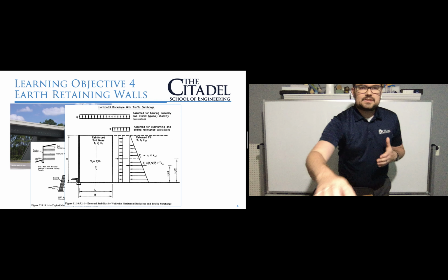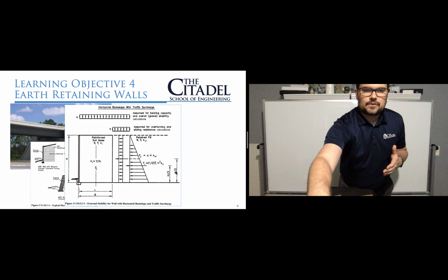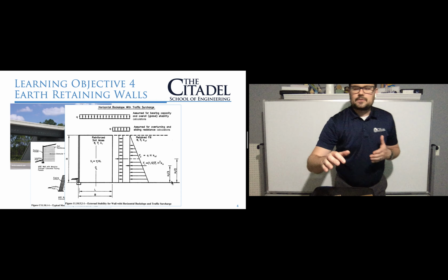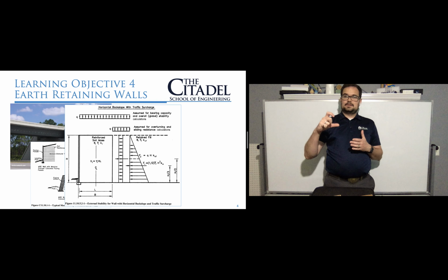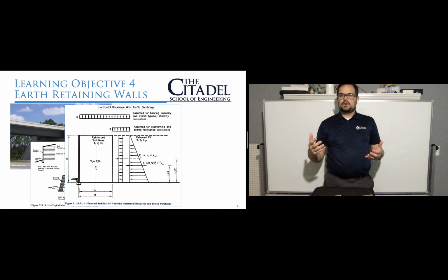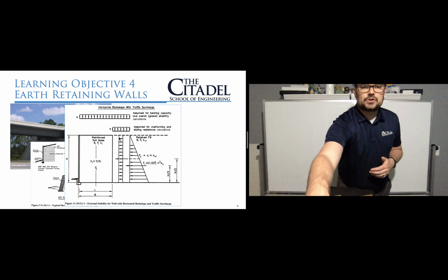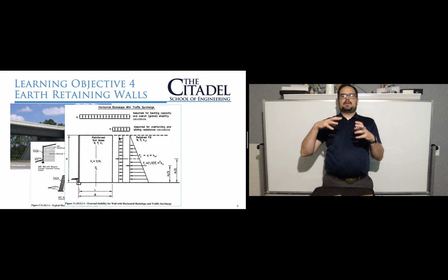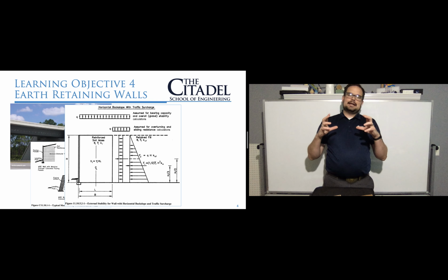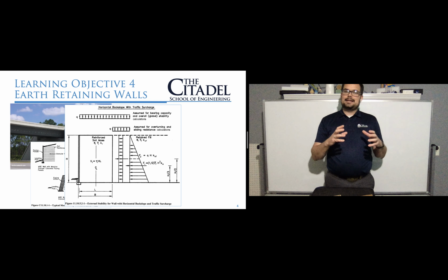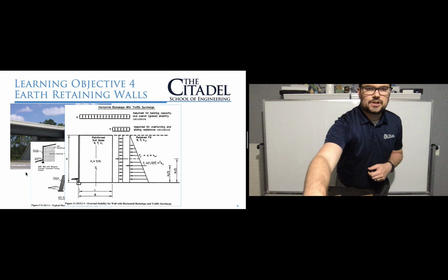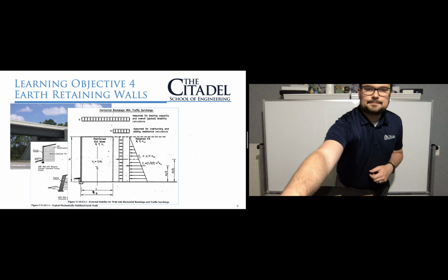So for example, you can see over here, this H over 3. What's that H over 3? Well, that's 1/3 base, or 1/3 the height in this case, to find the centroidal location for that triangular distribution. Likewise, the H over 2 gives us the traffic surcharge. So there's all these loads that get applied to the retaining wall, as well as gravity of the whole block to resist both overturning and sliding. And so that sliding is going to engage friction along the bottom of that block.